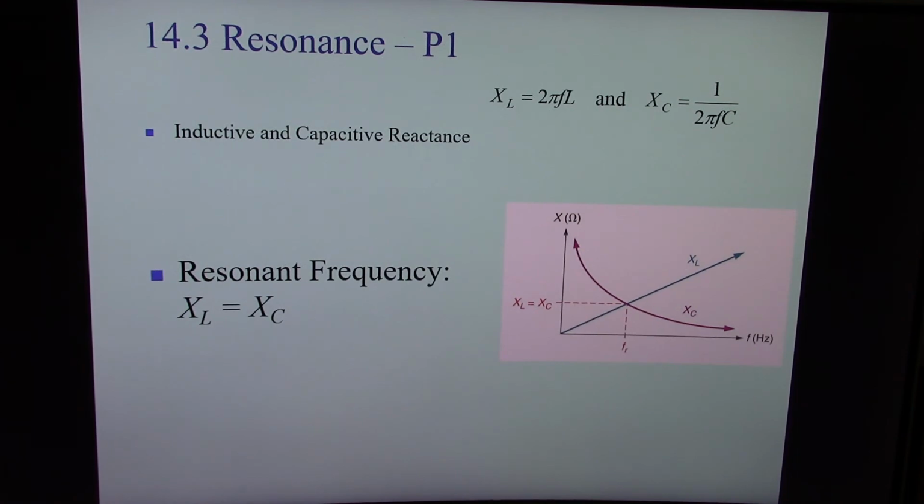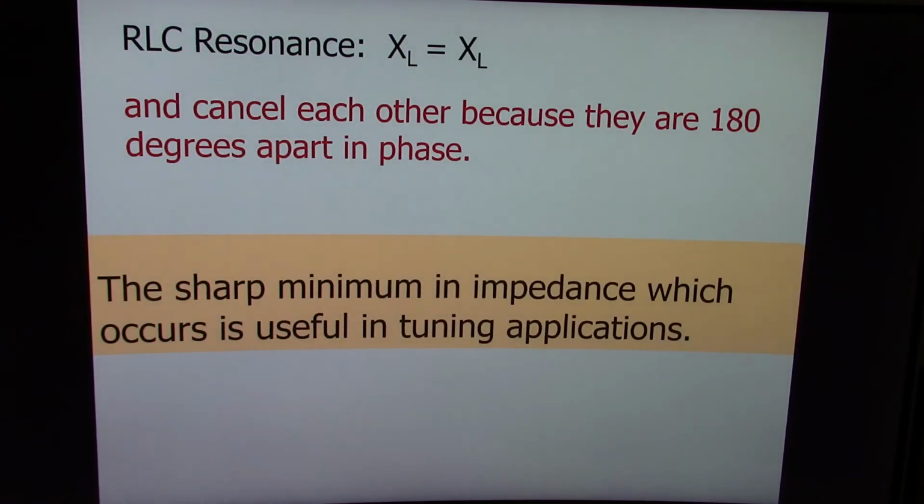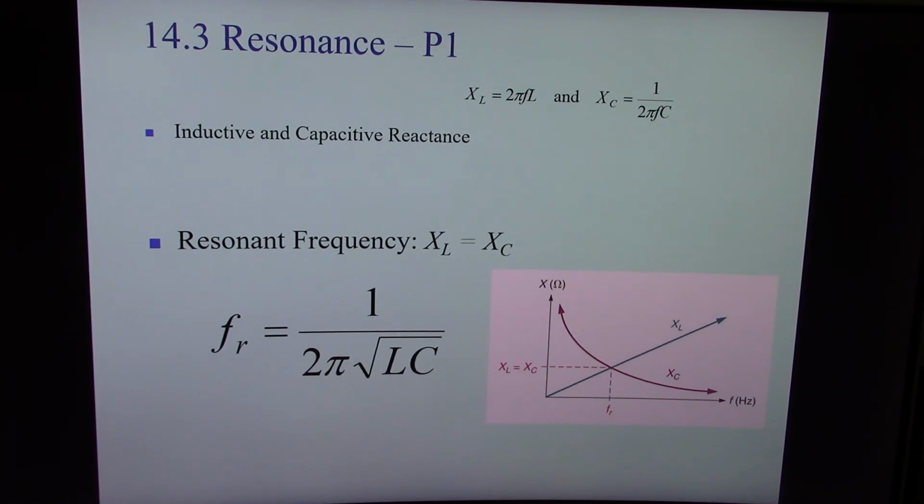And it's at that resonance frequency that you will get the maximum amplitude. So it's used in tuning applications. So the calculation for resonance frequency, F of R, is this formula, L being inductance, C being capacitance. Well, you can calculate these two also and get this, but it's easier to use this one.